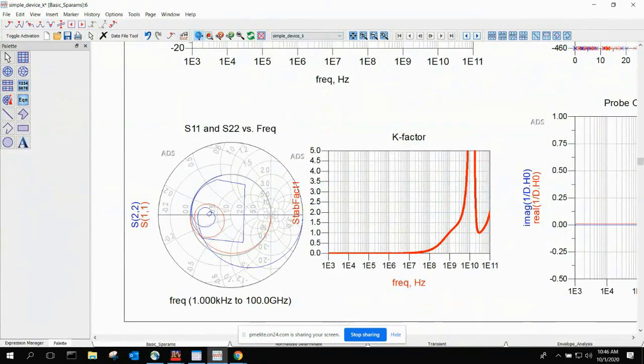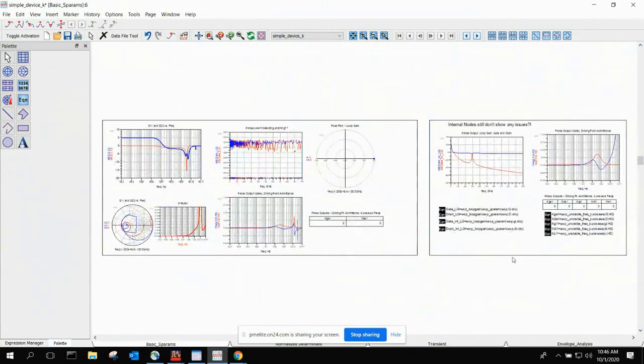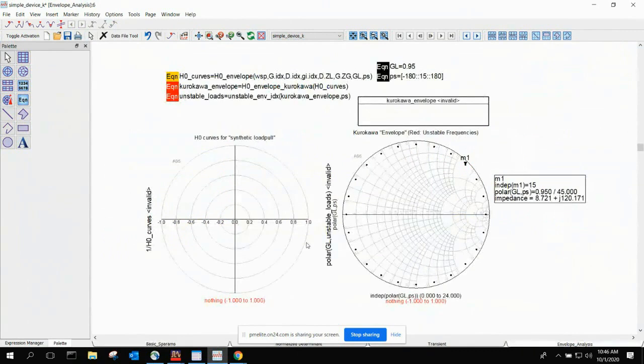So one thing that I wanted to show is how do you deal with that? And something that you'll see designers do pretty often, if they're designing these amplifiers, is what's called envelope analysis. Particularly with cellular PAs. I remember when designing cellular power amplifiers, these specs go back to the days when people used to pull out the antenna, you can extend the antenna out of your phone, and if someone broke it off, then the power amplifier would see like a 20-to-1 VSWR.